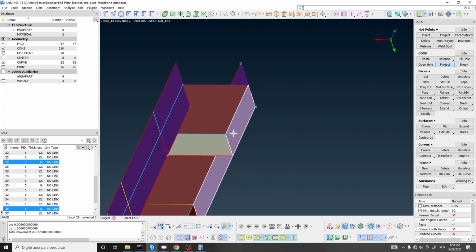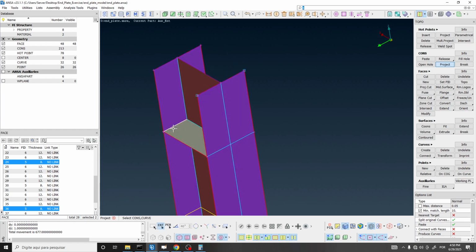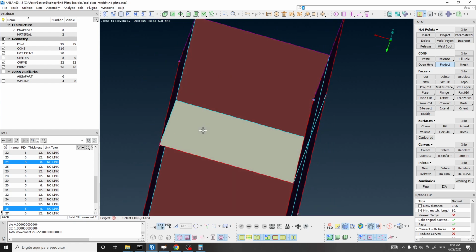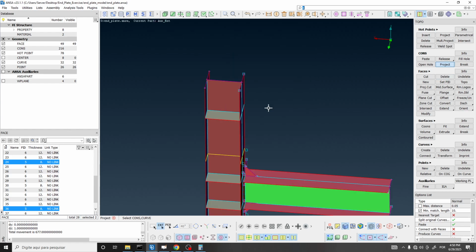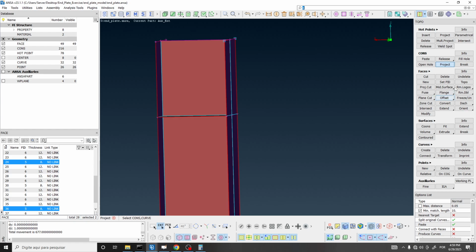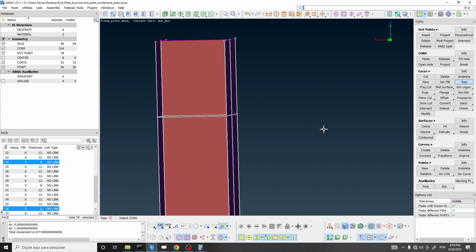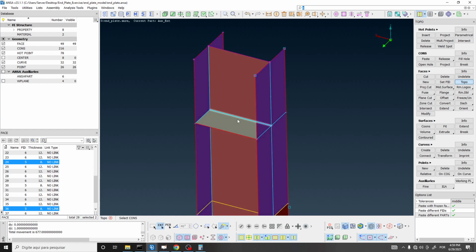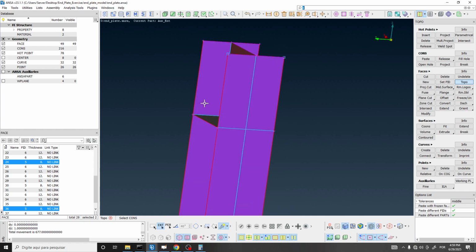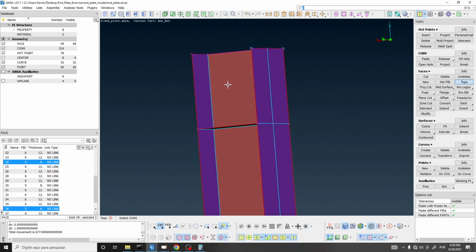This one, middle mouse button and this one. And there we have it. Let me see if there is another single cone here. To be sure that everything is pasted, it's better to use the topo tool in this case. Let's use the topo tool, create a box selection, middle mouse button. The software is going to recognize every cone that is too near to each other, and it's going to automatically paste them together. So now I'm sure that everything is connected here.